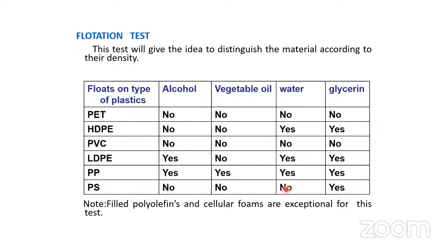Due to the density difference, it will sink in water. But if you take thermocol, which is again polystyrene, it will float on water. So these observations are limited to virgin polymeric materials only. If you have some other modifications, obviously these results will not hold, correct? Again, the example I have given here, like the filled polyolefins and cellular foams, are exceptional for this test.